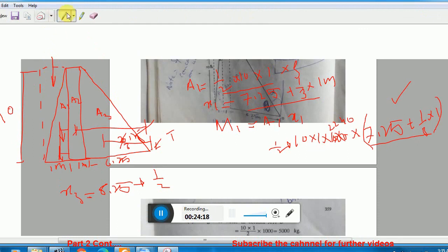Clear? Now this is the total weight, then you need to find out its moment arm. Okay, this will be its moment arm. So the weight of this water body we already determined in step 1. Now we need to find out this x. So you know the whole distance is 8.25. Clear? So from 8.25 you need to subtract this distance, and this distance will be how much?